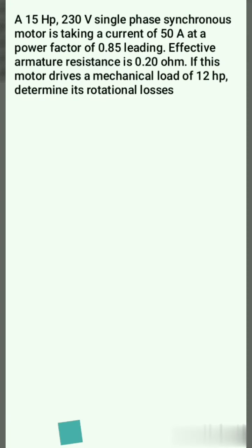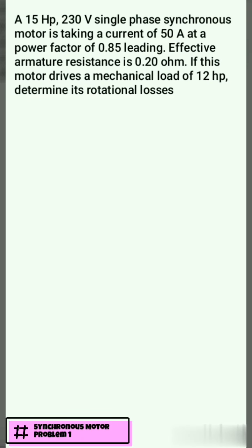A 15 horsepower, 230 volt single-phase synchronous motor is taking a current of 50 ampere at a power factor of 0.85 leading. Effective armature resistance is 0.20 ohms. If this motor drives a mechanical load of 12 horsepower, determine its rotational losses. So we have here the following given.